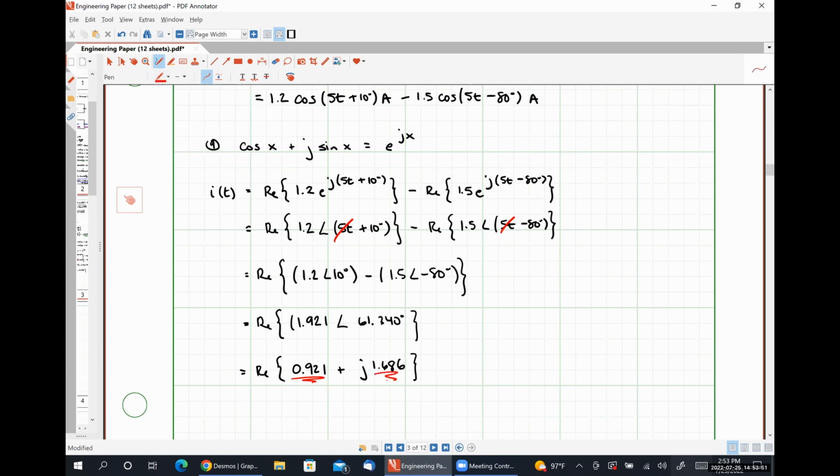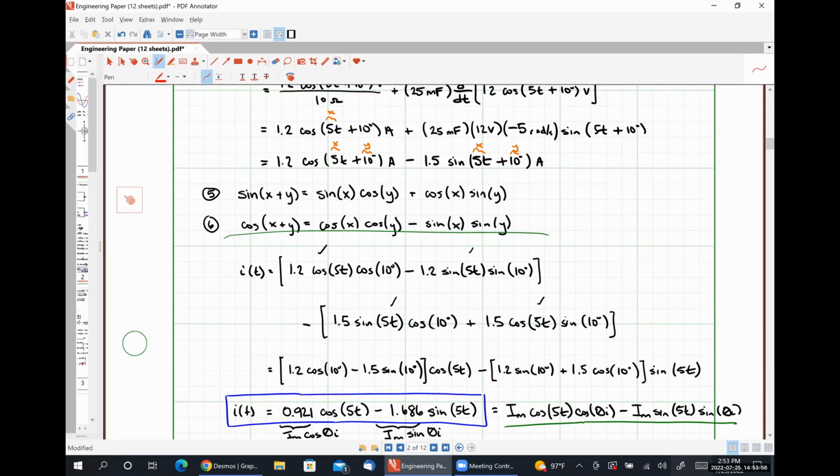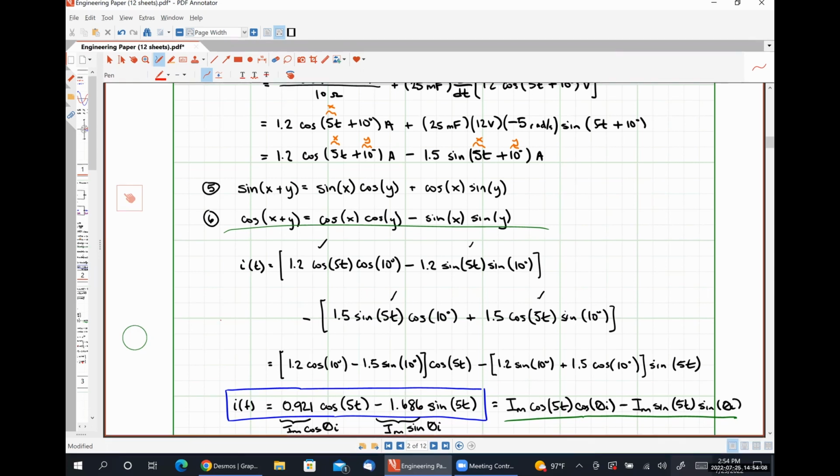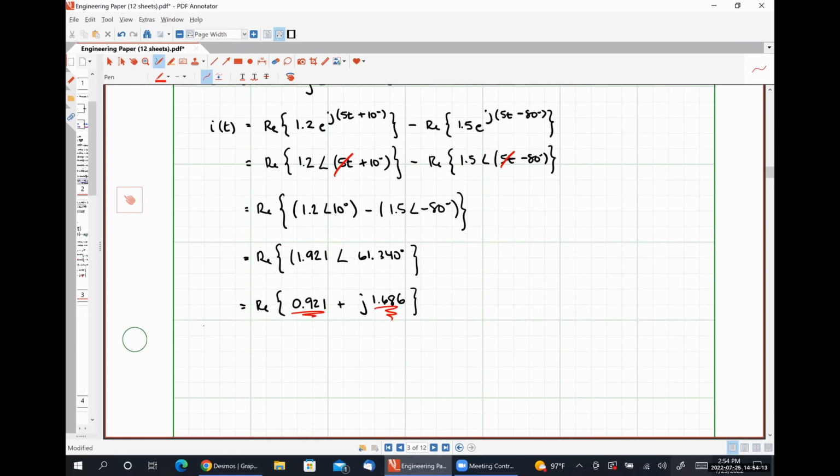These coefficients are the exact same thing as the coefficients we see here, except the sign on the imaginary portion is flipped. That is actually correct this time. And it's because of this trig identity. Now, the reason why I'm bringing all of these little relationships up here, we are going to use this complex number representation for all of our circuit analysis because it makes the math much, much shorter. But in your homework sets, you will be given,